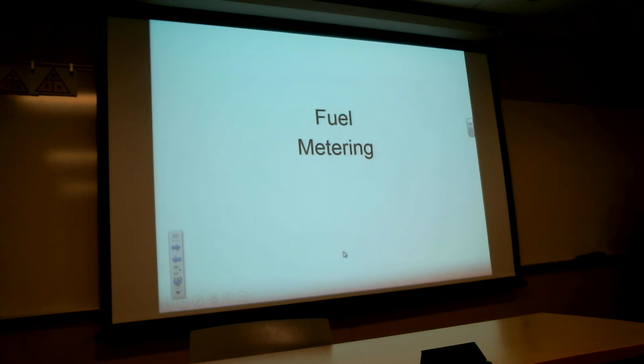Okay, so you kind of get a sense of how the FADEC systems work. So it's taking a lot of input information, computing it all together, and that's nothing more than what the FADEC is. It's just a computer you don't have a screen on, and it's taking all this information, munching it together, and it's telling the engine what to do based on what it sees. Okay? So it's going to give you fuel outputs, it's going to give you temperature outputs, things you're looking for. If the oil temperature starts getting too high, it's going to open a door to allow an oil cooler to operate. It may turn on extra oil scavenging pumps. It may do all sorts of different things. It's all part of the general health of the engine. So the FADEC controls everything.